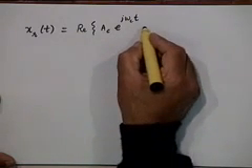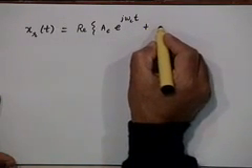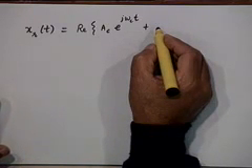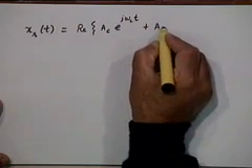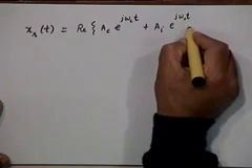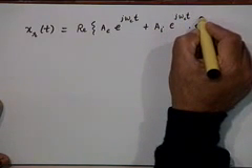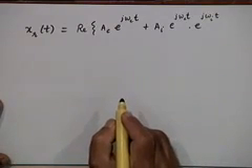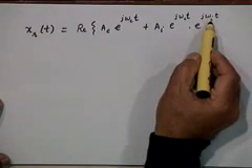Then there is this interfering component which is at frequency omega_c plus omega_I, the cosine of omega_c plus omega_I, that is A_I, real part of e^(j omega_c t) into e^(j omega_I t), because this is omega_c plus omega_I.